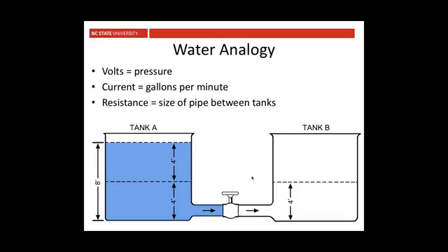One of the other things when we talk about choosing the right type of wire, you know, if you've got a wire, there's a little wire just hanging out on my desk, wires have an insulation, right? Plastic insulation on the wire. And why and how? Who decides how thick this insulation is or what type of insulation it is? Well, the job of the plastic that covers your wires is to stand up to the pressure of the voltage.